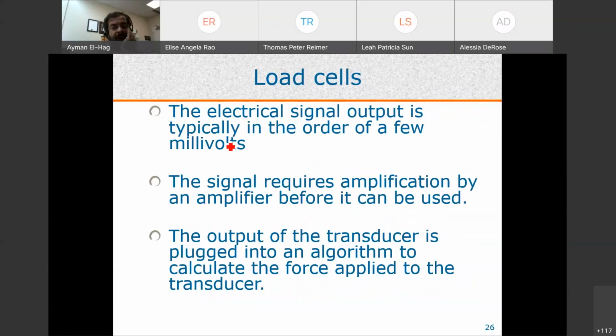Now, the voltage that we get, as we have seen in the previous examples, is in the range of the millivolt. And this is a problem here. Why? Because when you have a very small voltage in the millivolt range, sometimes you have noise around you. Sometimes the noise is even more than this voltage. So you need to get this signal amplified. And this is what we will be studying later on using the amplifier, and we will see next week when we talk about temperature sensors.